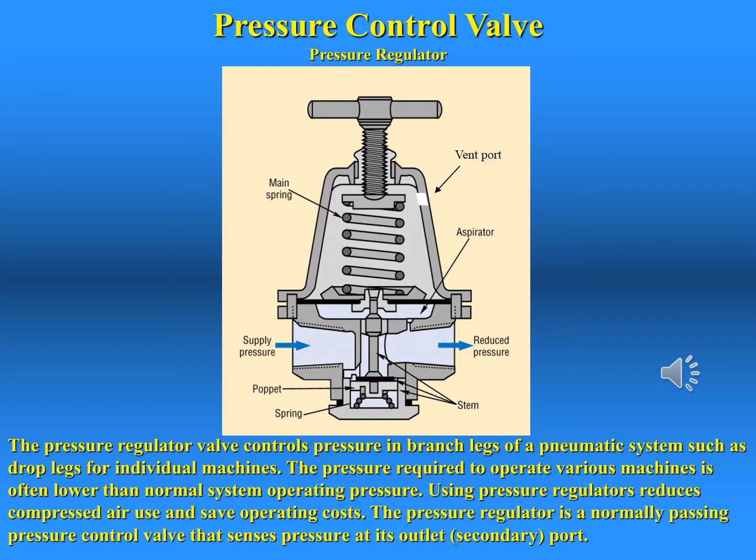If downstream pressure rises above upstream, the valve will release it into the atmosphere. When excess pressure is released, air moves through the tiny opening in the secondary port, lifting the diaphragm off the top of the stem and allowing air to escape through a tiny hole in the upper housing.